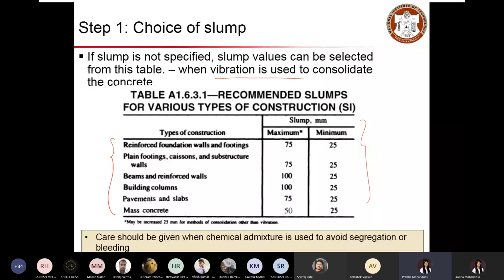In the next lecture, we will look at the handling of concrete during mixing and placing. Just to have an idea about these vibrations, there are different types of vibrating systems. In certain places you use a rod, which is typically manual vibration. You can just hold the rod and tamp the concrete. In other ways, you have needle vibrators. You can place the needle and use that vibration to compact. And there are table vibrators, and different types of vibration available for consolidating the concrete.